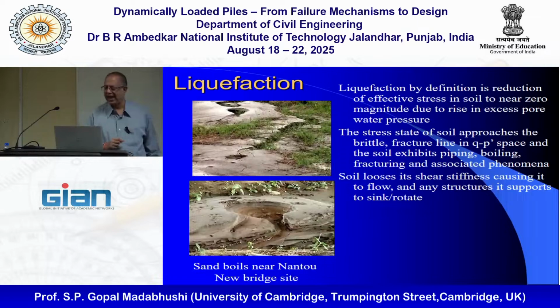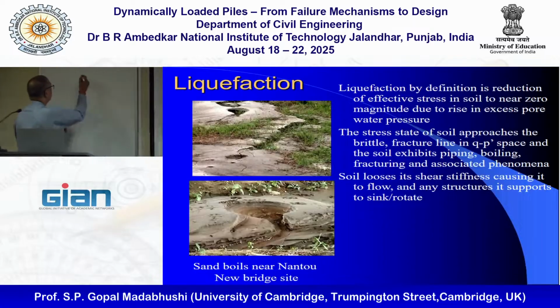But what we can model in the centrifuge is not just the soil behavior and sand boils and all those things. I even showed you examples of where we could see this in the experiments yesterday. But really, what we are interested in is, if there's a building that is constructed on soil like this, we can predict how much it will settle and rotate. So you can plot.